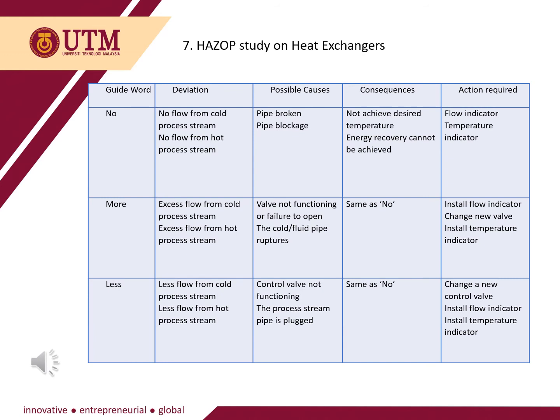Lastly is the hazard study on the heat exchanger. If there's no flow from the cold process stream or from the hot process stream, we cannot achieve the desired temperature and energy recovery cannot be achieved. So what we can do is install a flow indicator and temperature indicator.